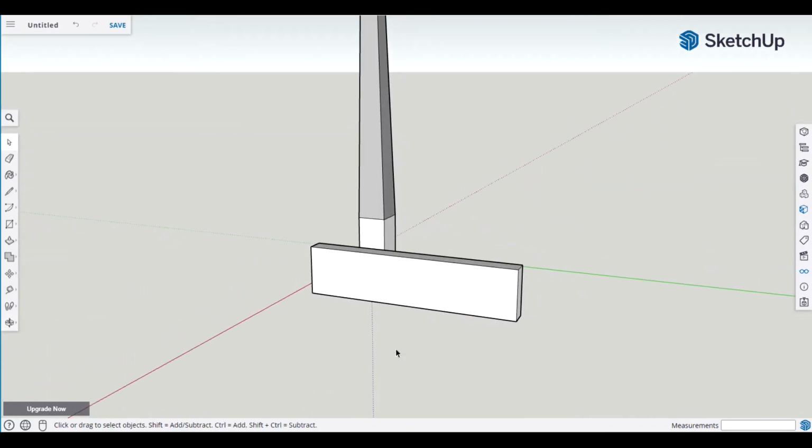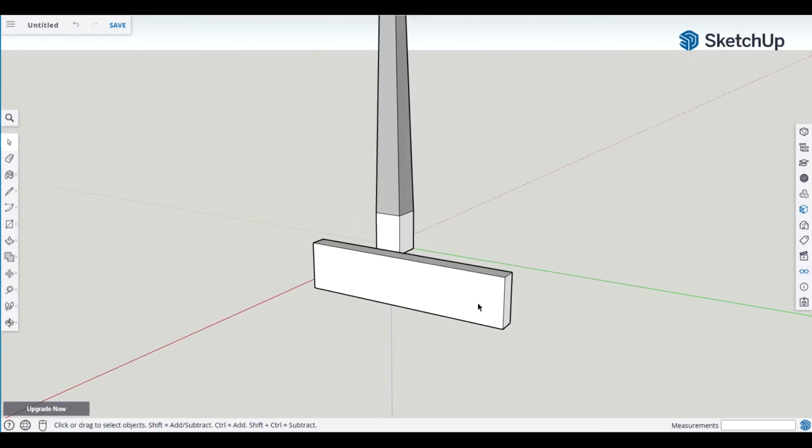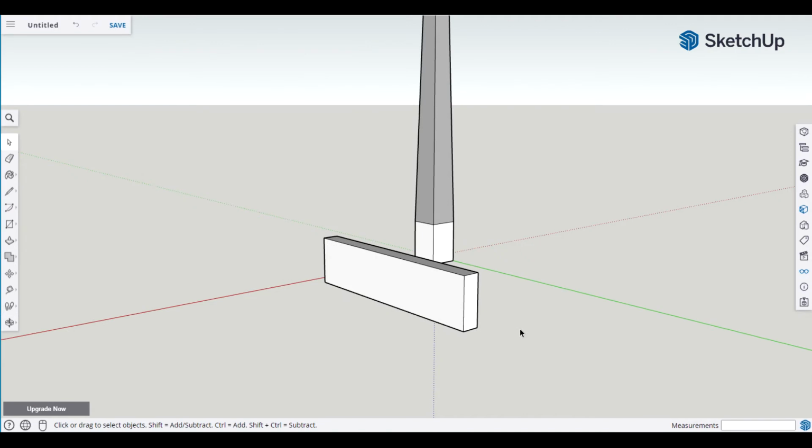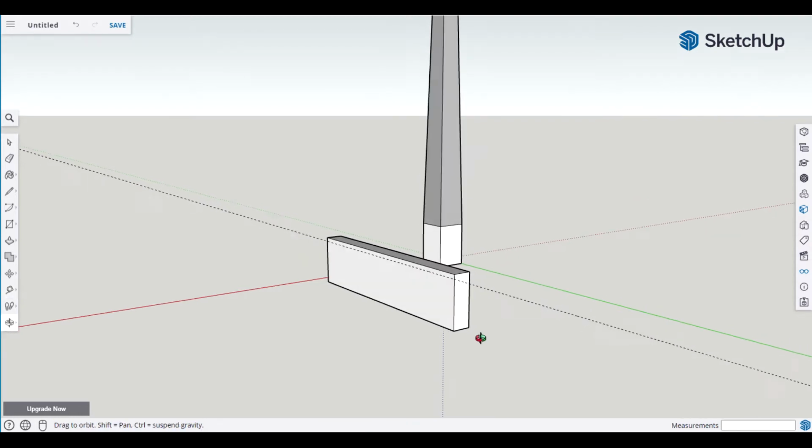Next, I want to do a 1/4 inch groove. Now remember, the leg is upside down, so the 1/4 inch groove is going to be on this side here. So when we attach it, it's towards the bottom of the leg. So let's select the tape tool because we're going to do a 1/4 inch guideline going down, 0.25, enter, space, rotate it a little more.